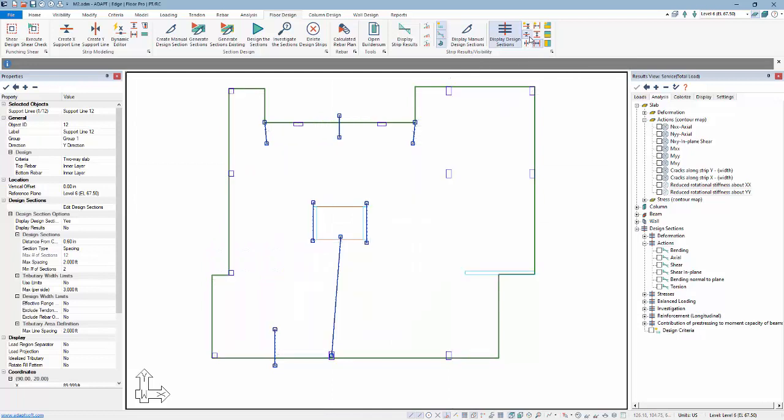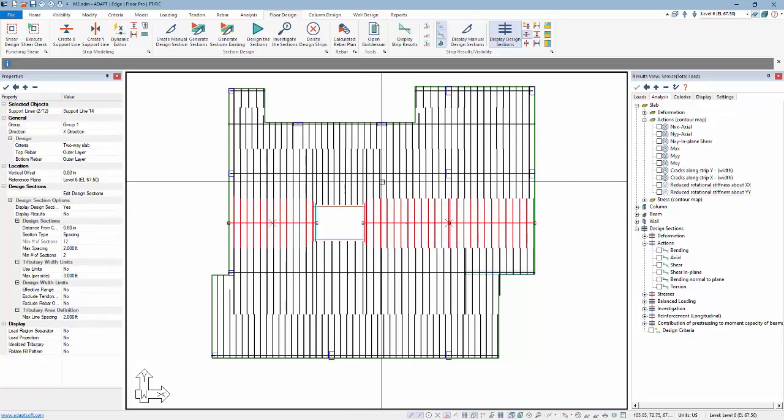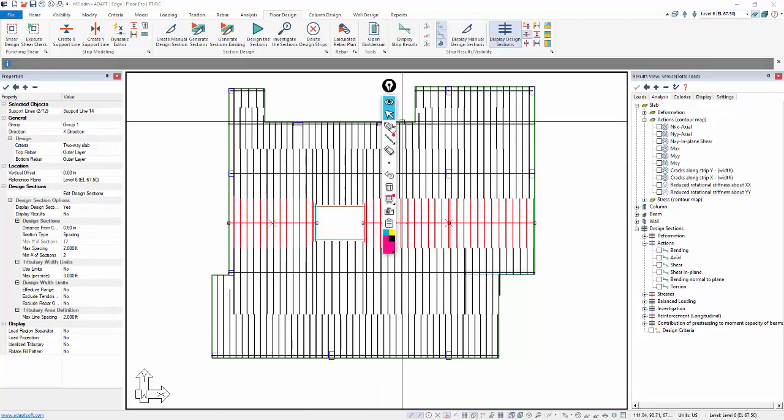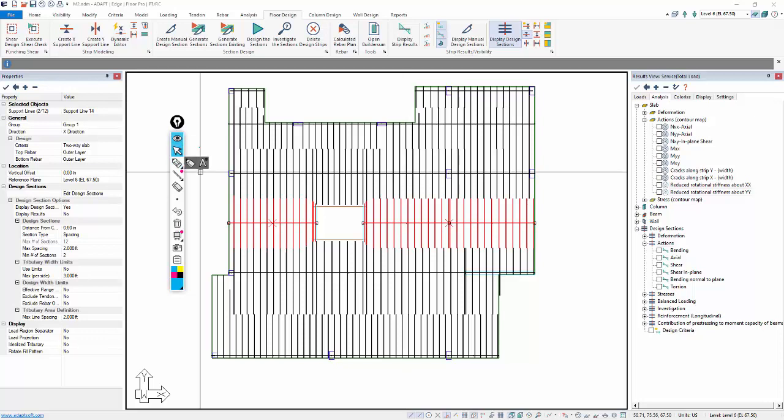In the other direction, in the X direction, we added a couple of strips here and over here just to refine the design cuts. Earlier the cuts were being integrated really from here all the way down to here and then like so. So we just brought in this cut and this cut just to break that up slightly. This is a uniform direction, so we still have uniform cables through this region here. We have banded cables. Let me color that in blue on the outside, so these bands pick up the uniform cables in the X direction for those new strips that were added.